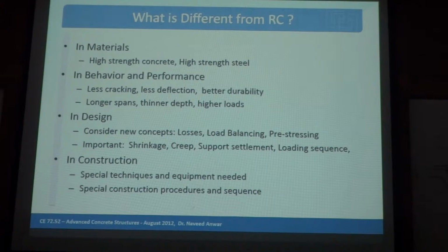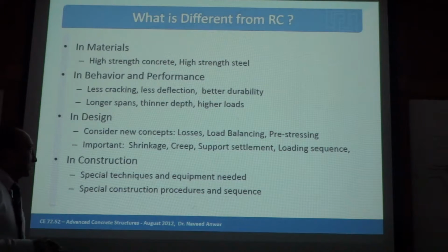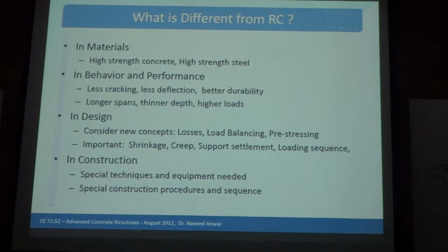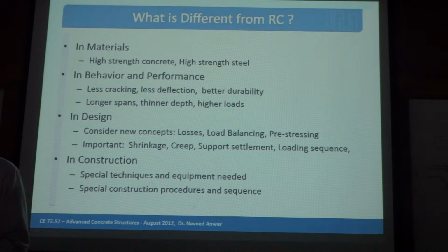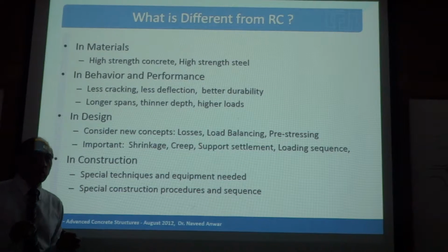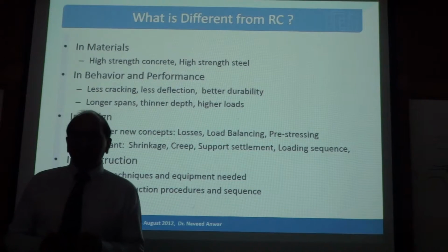In design, we consider new concepts: losses, load balancing, pre-stressing, shrinkage, creep, support settlement, loading sequence. These are all important things because now we are dealing with a completely different concept, not with normal concrete. This reinforcement, this steel that you put in, is not passive, it is active.